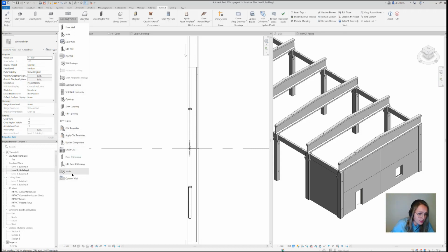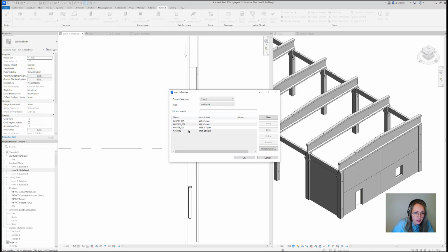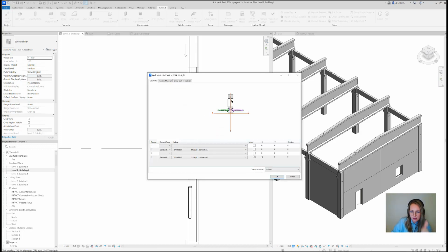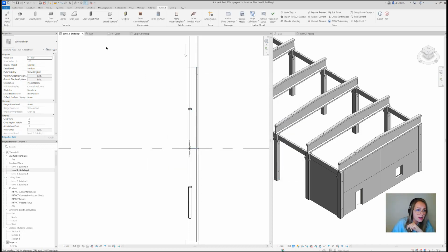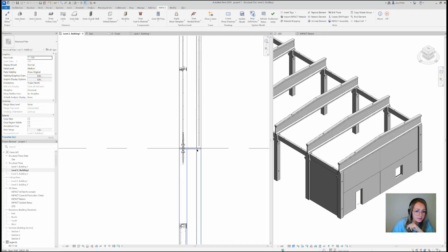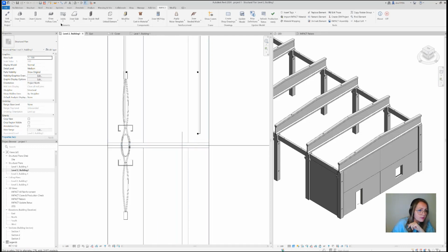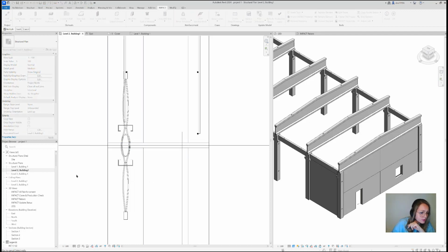Basically, what a joint gives you is end geometry, spacing between the walls, gaps, and inserting of casting materials in one. So if I go now and say connect wall, that's where we're using the joints.